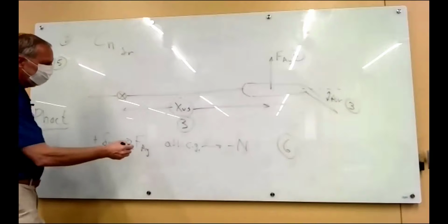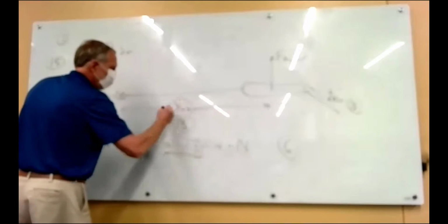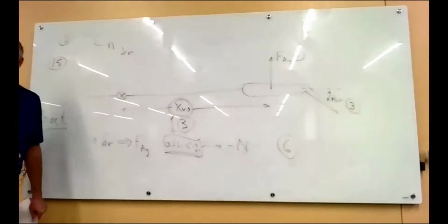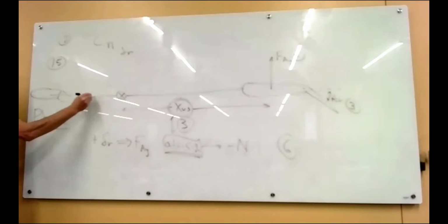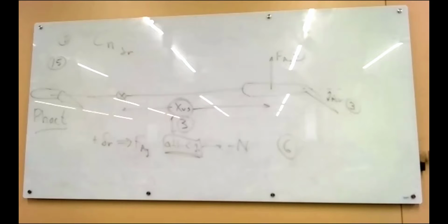A key thing that I saw people missing was talking about how the moment arm gave you the negative yawing moment. And that's really important because you could have a vertical tail in front, and I think we had a homework like that, right? So if the vertical tail were in front of the CG, the rudder would produce a positive yawing moment. All right, you had a question. If you have specific questions about things that maybe I missed, see me. Yeah. I'll be happy to look at it. It's just I don't want to spend class time looking at your particular. So that was 15 points.